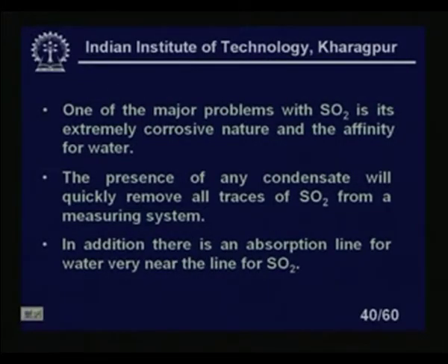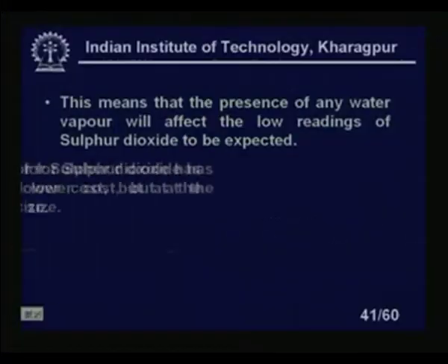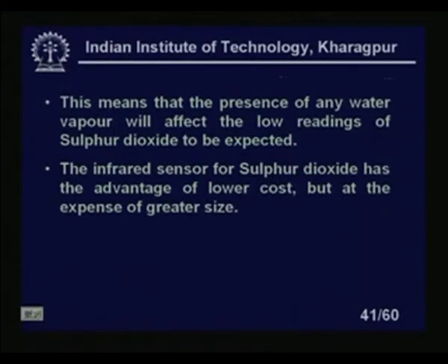In addition, there is an absorption line for water very near the line for SO2. This is another problem. This means that the presence of any water vapor will affect the readings, and low readings of sulfur dioxide are to be expected. So not only the reaction, but this line also lies very close, so there will be low readings of sulfur dioxide in the presence of water, whether water vapor or steam, whatever you call it.